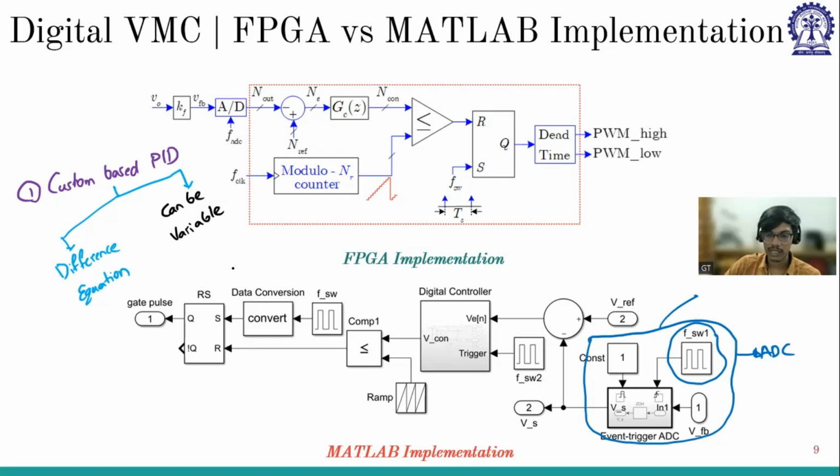So there will not be any synchronism with that. Say the switching frequency of the converter is more than the frequency at which this is changing, so the converter will operate at higher switching frequency, but the control voltage will change after a few cycles.